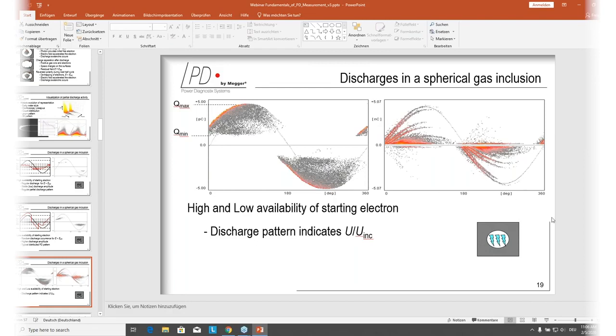The next is about whether IEEE standards exist for PD measurements. That means, are there standards available for partial discharge measurements? Yeah, the answer is yes. There are multiple standards from IEC and IEEE, including PD measurement methods and procedures for testing high voltage assets, mainly in the factory for quality acceptance tests.